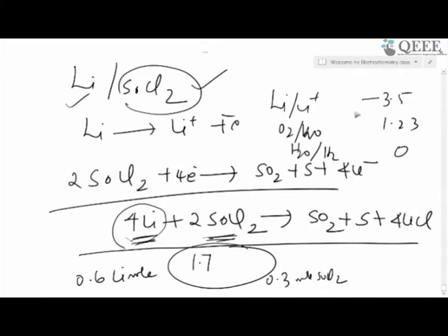So, in any case, lithium will be the anode and these things will be the cathode. That means lithium can react with oxygen, and lithium can react with water also. Because of this process, lithium will violently react with the ambience and it may cause harm to the person who opened that cell. Hence, these kinds of batteries are always made anode limited.